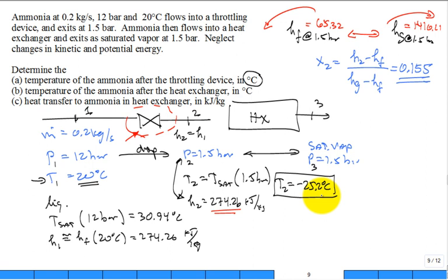There's no heat transfer in this device. There's no work transfer in this device. How did that work? You really need to think about that. I encourage you to think about it. What was the big change? Pressure. When it dropped pressure, what did the fluid want to do? Vaporize. Some of it did vaporize, but it takes energy to vaporize fluid. And so it came at the expense of the liquid's energy, and the whole mixture dropped in temperature because some of it vaporized. It is really incredible that you have vapor compression refrigeration systems that work.